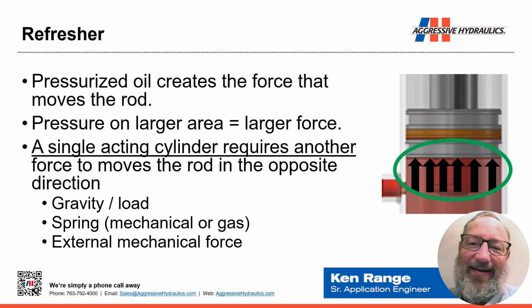We've got to remember that any single-acting cylinder will require an external force to get it to move in the opposite direction. Because they typically extend, it would take that external force to cause that single-acting cylinder to retract again.